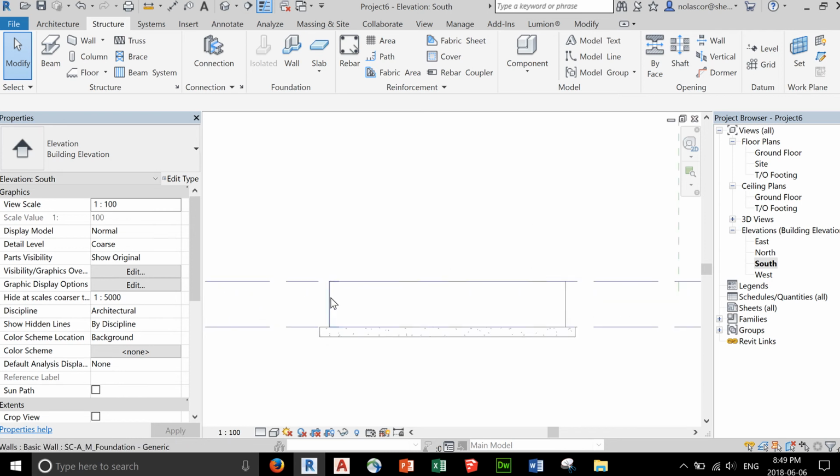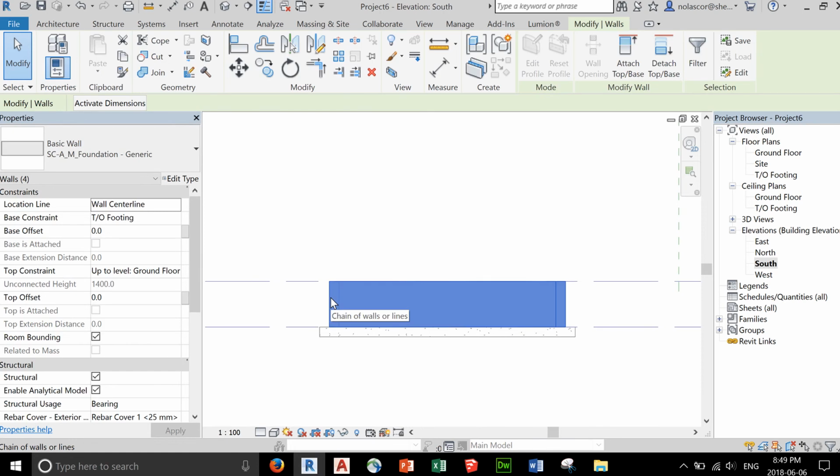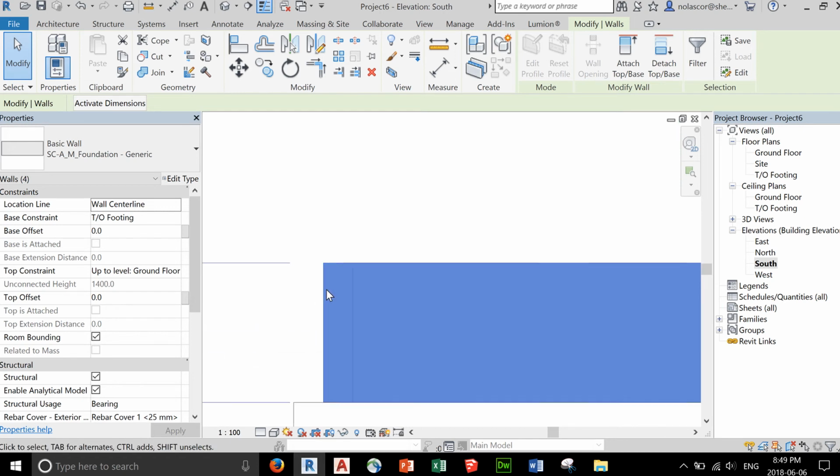Okay, so again, hover over one, hit the tab key, select, and you might want to bring this down to the level where you will support and add the thickness of the wood joist and the wood plate. Okay, so that should have a total of 292.1. So I have pre-calculated that.